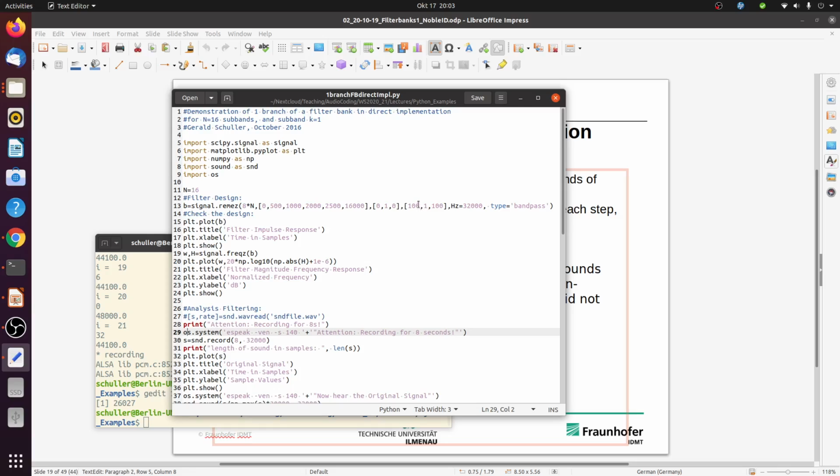And that means here this factor of 100 means I find it very important to get good stop band attenuation. So this should be very close to 0. I don't mind a little bit change from the desired 1, so it can be 0.9 or 1.1, that usually doesn't matter. But I really want to have a stop band which is like 1/100th, so 0.01 for instance. And that's why I chose those weights.